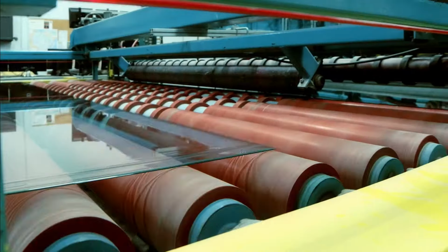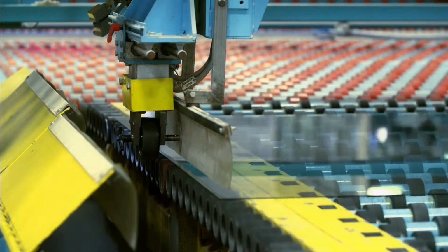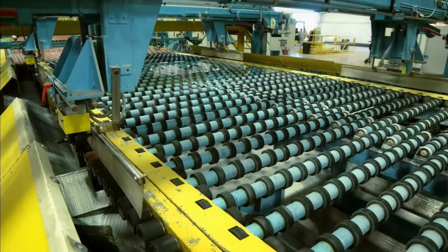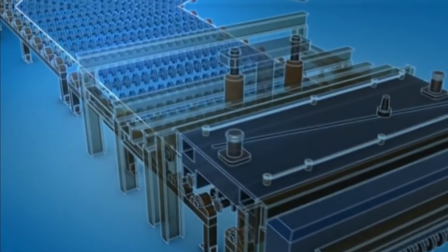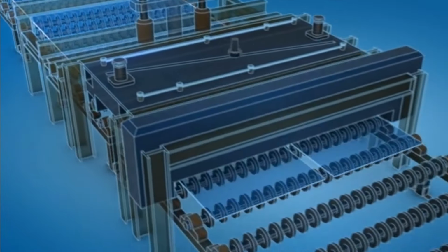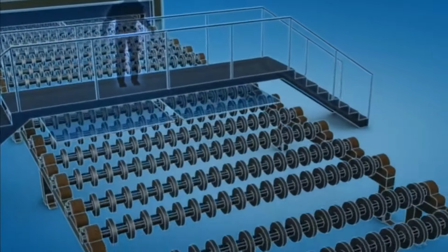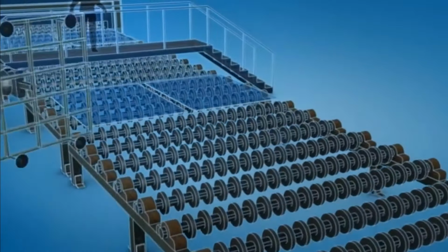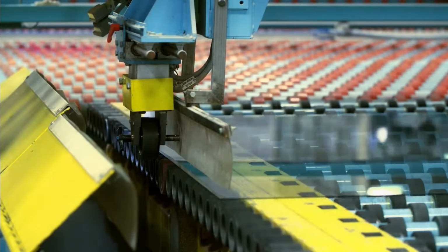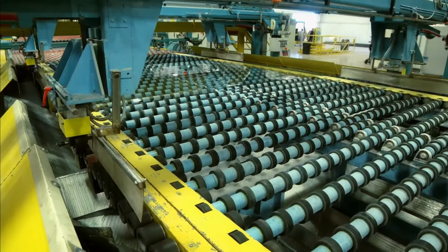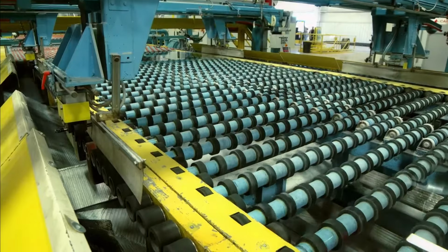The XY cutter is a specific equipment that creates a tiny, continuous scratch on the glass surface from one end to the other edge. This method, known as scoring, provides controlled glass fracture along specified lines. During a bump roll, the scored ribbon splits apart or is divided into smaller glass sheets. The edges are then trimmed. If the glass edge remains untrimmed anyplace, the laser technology identifies this flaw. The faulty sheet is sent to the batch house for recycling.